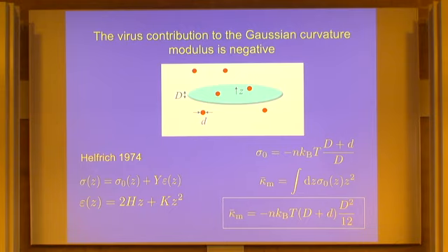There's a similar kind of argument that Helfrich put forth for a fluid membrane, which is a little bit different than the solid plate because it's not a solid. The physics is a little bit different, but it relies upon the same geometry, which is that when you bend the surface, the strain in the surface as a function of the distance z from the middle of the surface is going to depend on the curvature.